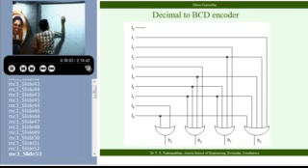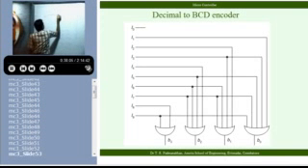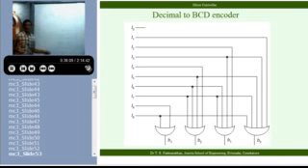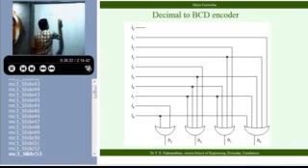The sample will be taken at time t0, that will give you a value x at time t0. That will be an analog value. This you convert into equivalent digits, say a 10-bit digit. That's a binary number.